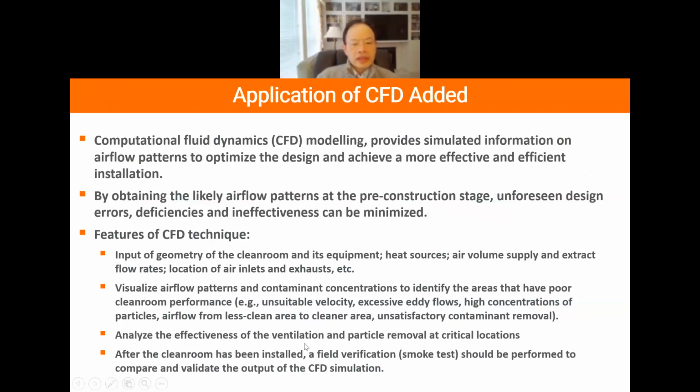And also analyze the ventilation and particle removal at critical locations. And after the clean room is installed, a verification, a visualization, is required. Typically, a smoke test should be performed to compare and validate the output of the CFD simulation.